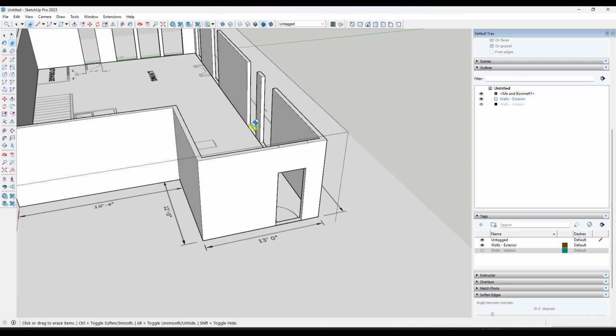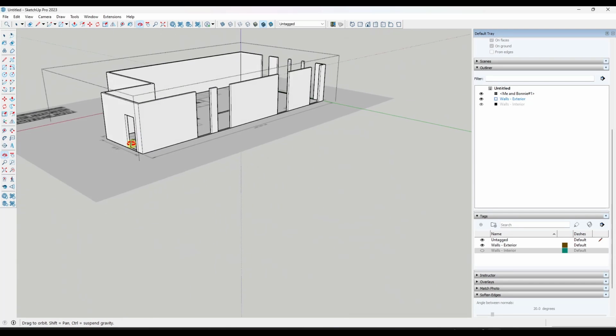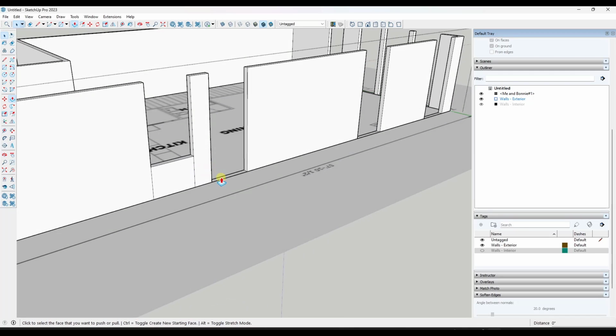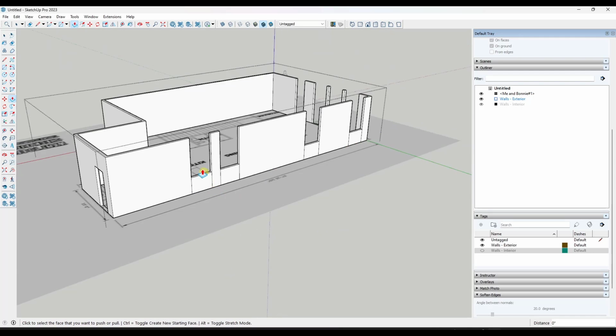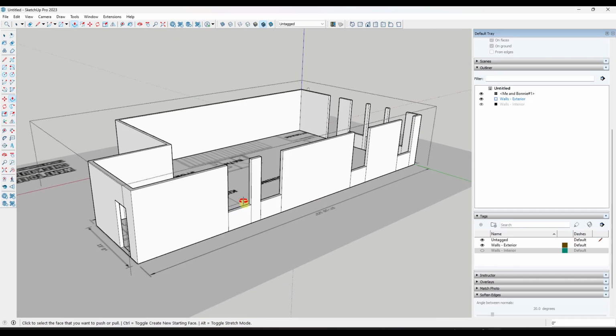But with the windows, you need to push pull them up first. And honestly, that probably makes them a little bit easier, because what you want to do in this situation is push pull this up to whatever the height of the bottom of the window is going to be. So we'll say 36 inches in this case. And so you want to push pull that bottom piece up, and it may be better to go around and push pull all of your window geometry up to that same height, just because you can keep using that push pull tool in order to do that.